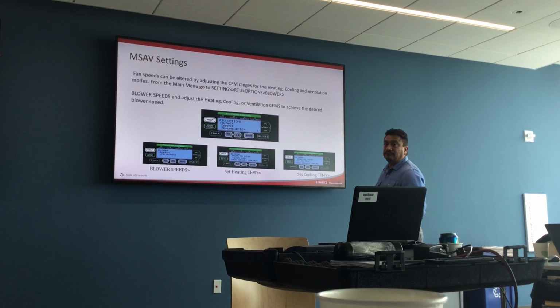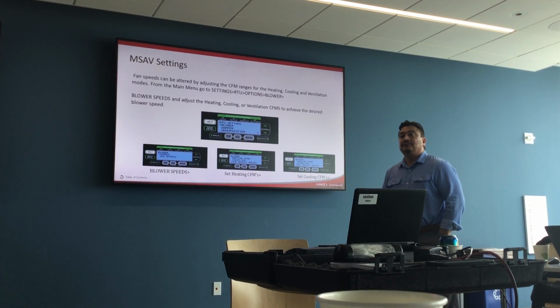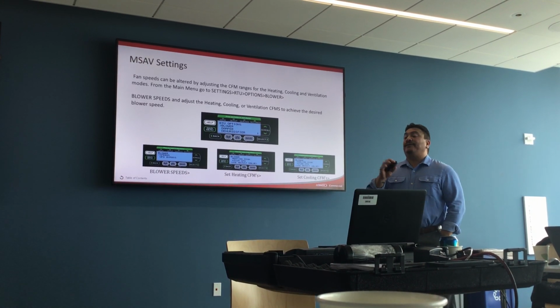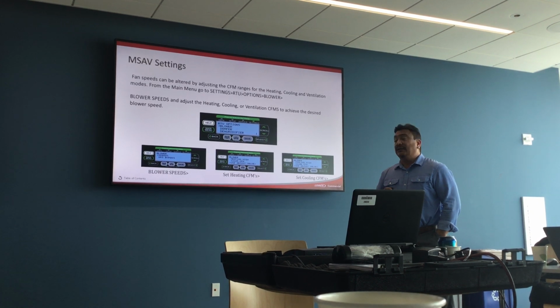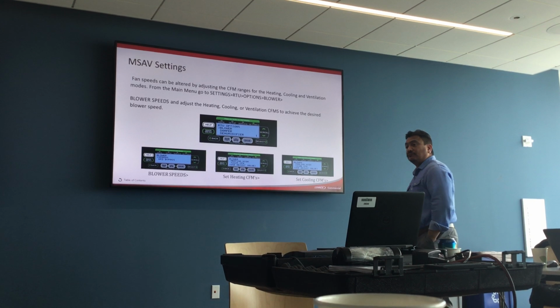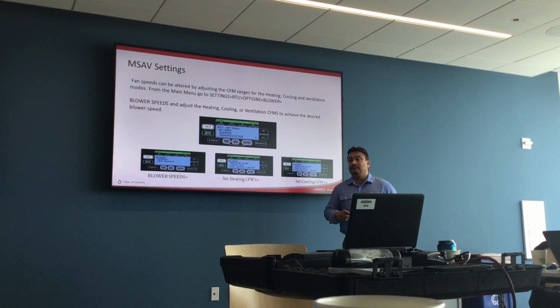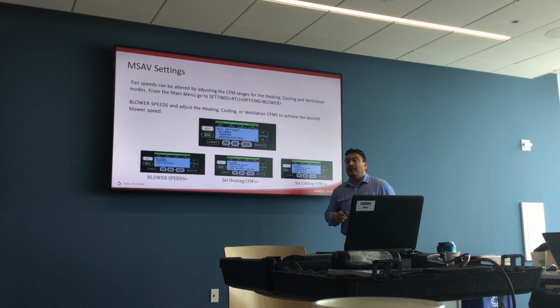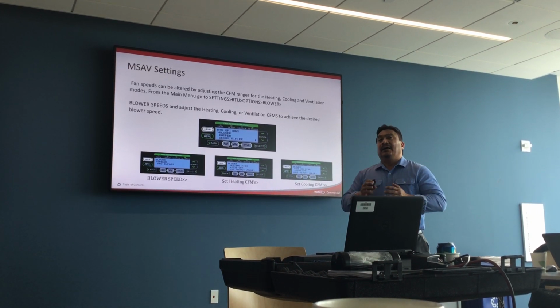Now, I'm sorry, I don't mean to interrupt, a question for that last one. So you're saying if it's operated off of a thermostat, it has to have that jumper on there? No, the idea is that if you are using a non-commercial grade thermostat that does not have an EC or occupancy, then you have to put that jumper in place. Gotcha, okay. So when they field install their thermostats, they should have a line coming from there to whatever, say, our BMS or thermostat, right? Correct. And let me clarify a couple things.